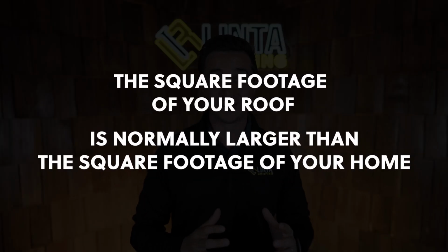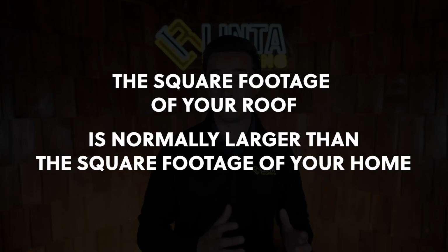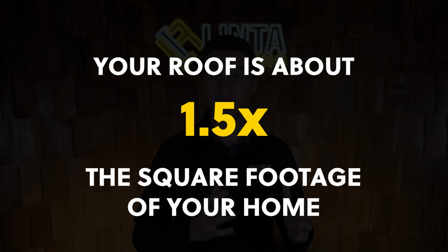Keep in mind, the square footage of your roof is normally larger than the square footage of your home. On average, your roof is about 1.5 times the square footage of your home. If your roof is multiple stories, then your roof is normally 1.5 times the square footage of the first story. So, if you have a 2,000 square foot home or 2,000 square foot first story, your roof is normally around 3,000 square feet, depending on the pitch and shape of your roof.